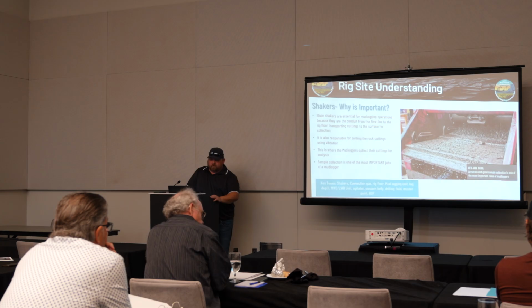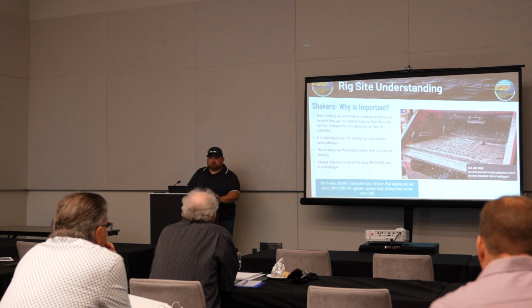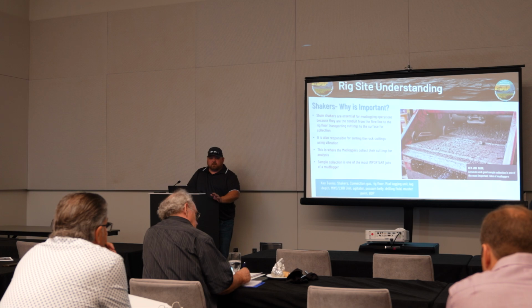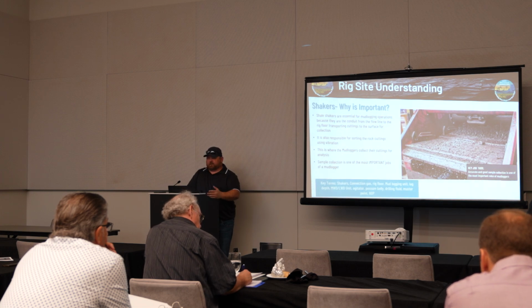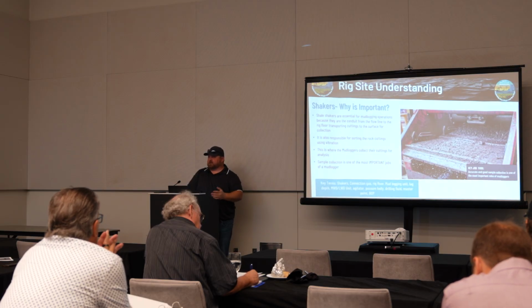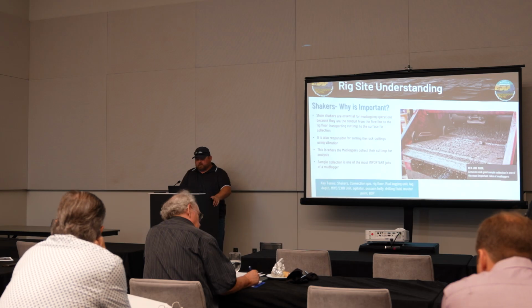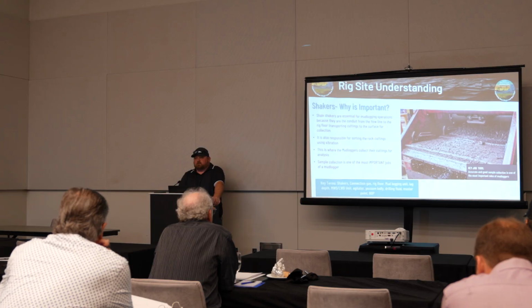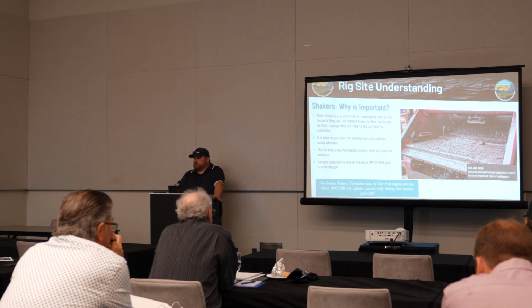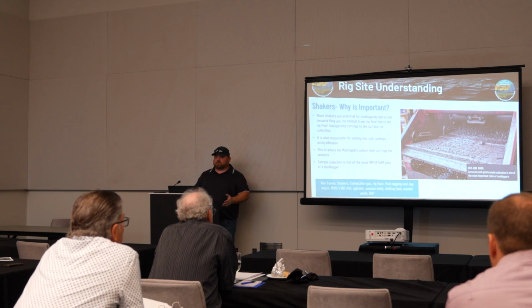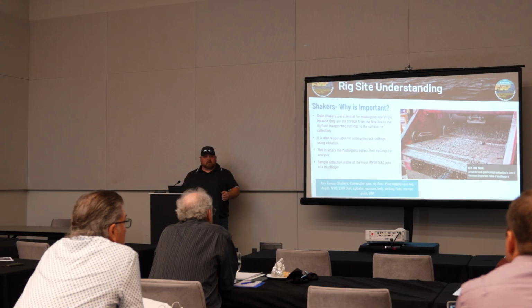Shakers are real important. That's where we collect our samples from 99% of the time. The only other time you won't is if they're fighting lost circulation and we're having to catch it either off the end of the flow line or in the possum belly, and they can't run it over the shakers because they don't want to lose LCM. LCM being lost circulation material. Usually we'll put a board or a bucket at the end of the shakers to do a comprehensive sample of the entire interval. So if, say, you're catching 30-foot samples, you don't want to catch a sample in...